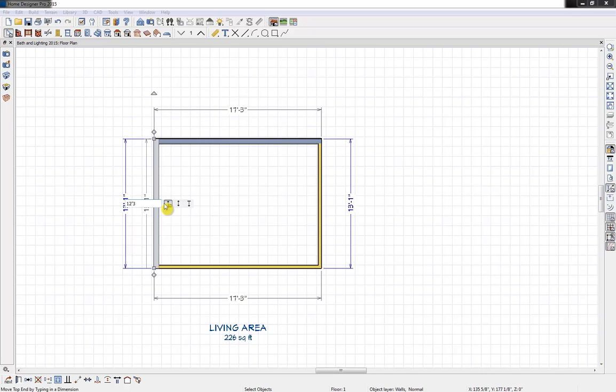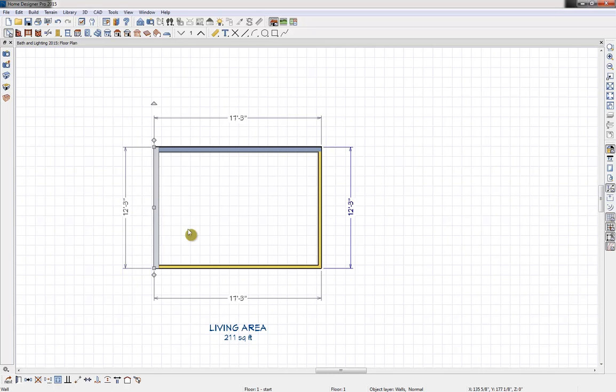And then we have some different controls here on how we'd like to modify that wall. So I can either move the top, or move both ends, or move the bottom. So I'll keep that selected for move the top end. I'll hit enter and that'll bring it down a bit. Next, let's use our perpendicular dimension here. Just single click on that, type in 17 feet 2.5 inches. So you can use decimals or fractions, however you'd like. Just hit enter and now our space has been completed.